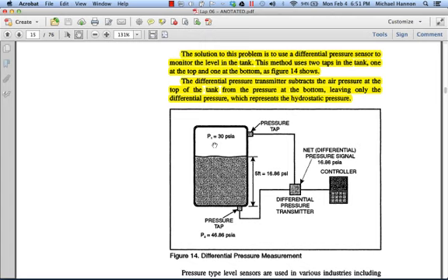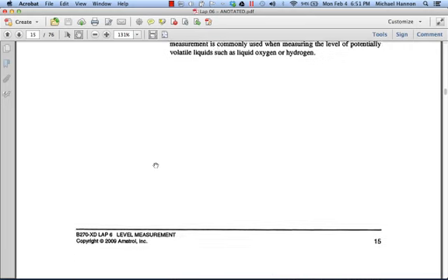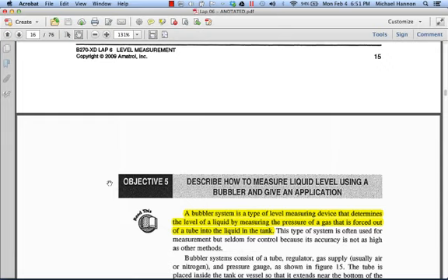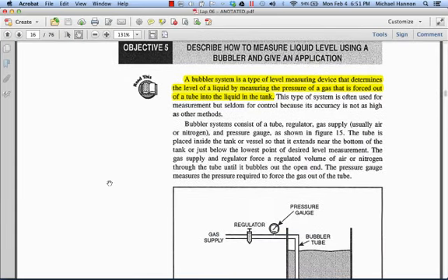If the RCS pressure reduces to less than 650 pounds, these accumulators will dump directly into the reactor, so that we have a great big concentration of borated water that will fill the reactor totally up, so that we can reduce the fission process within the reactor vessel.